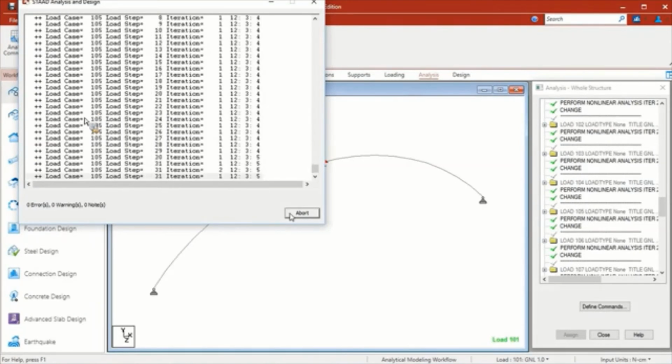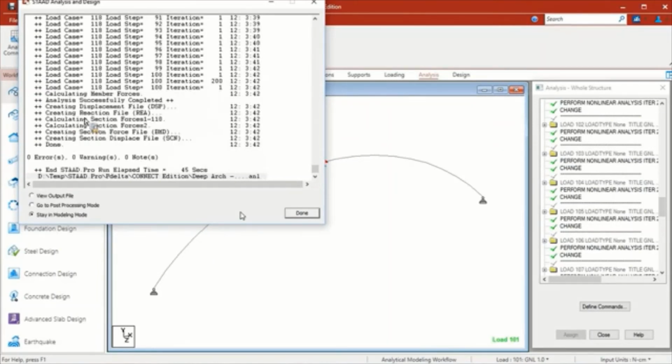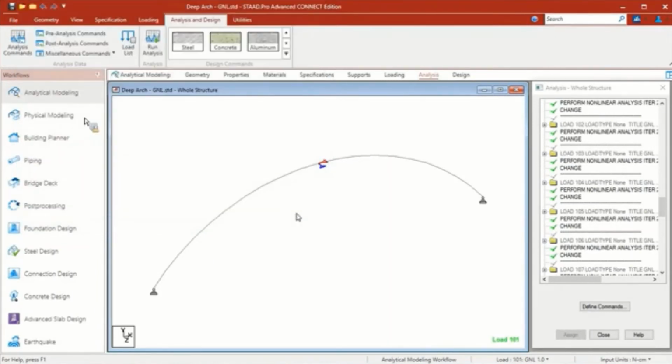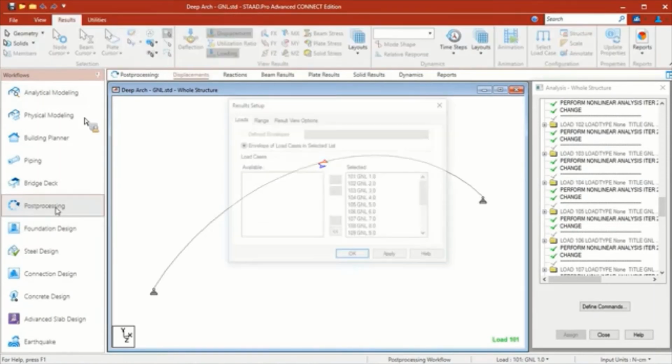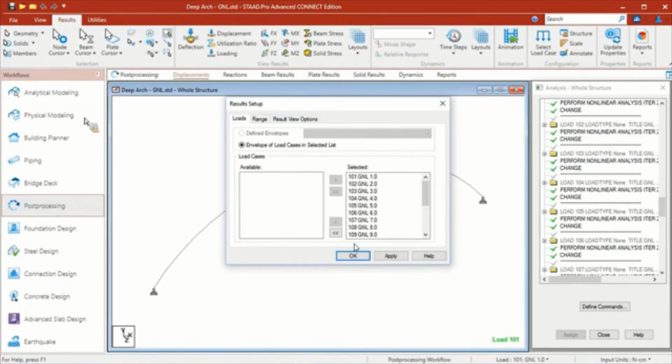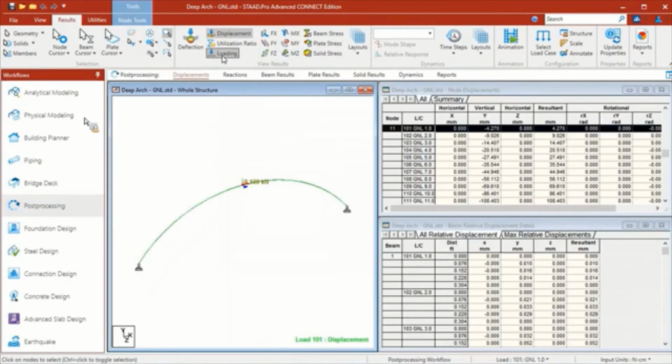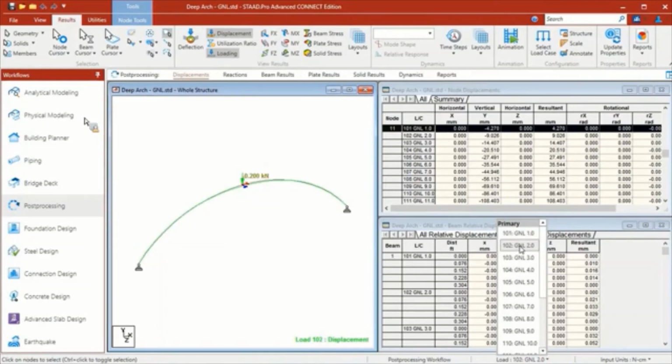We've got the capabilities of doing a dynamic analysis or a response spectrum extraction and solution for seismic type events. But I'm sure you often find now, more and more your requirements are to go beyond the basics of a standard first order elastic analysis, or even the basics of a P delta, accounting for those effects that take place during the analysis on more slender models.